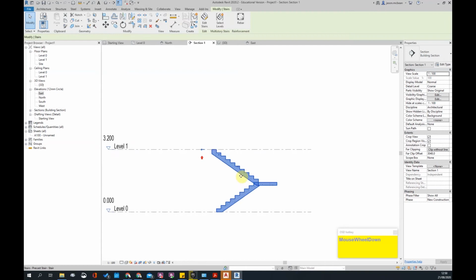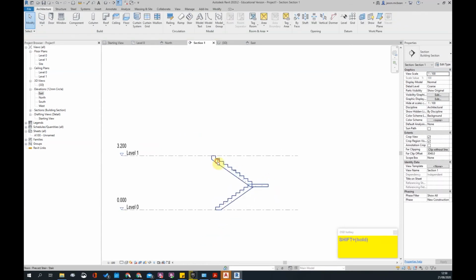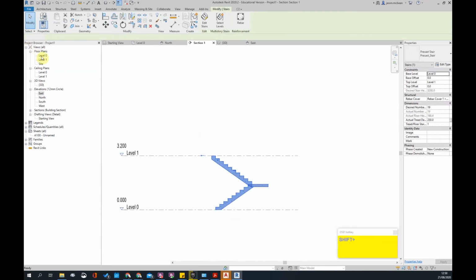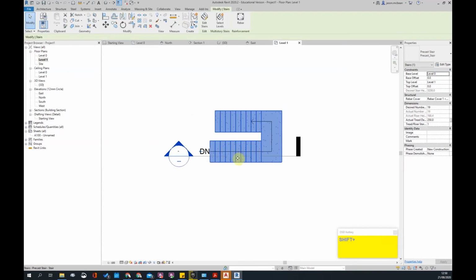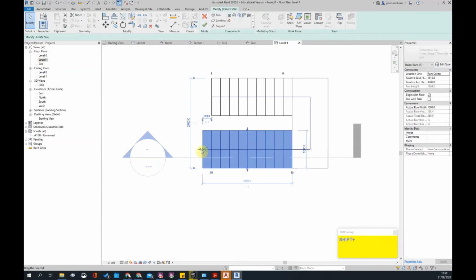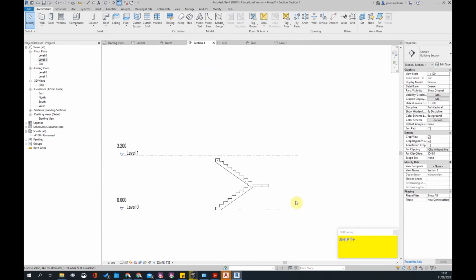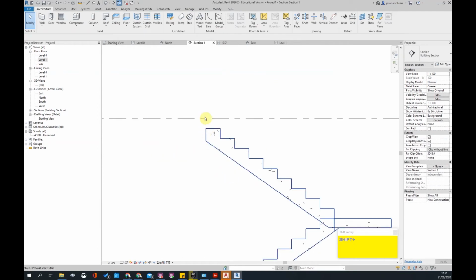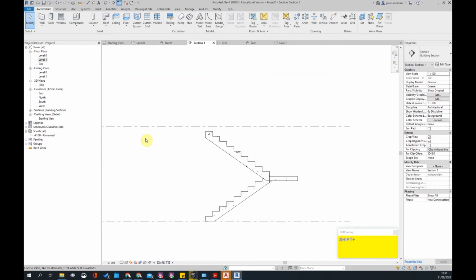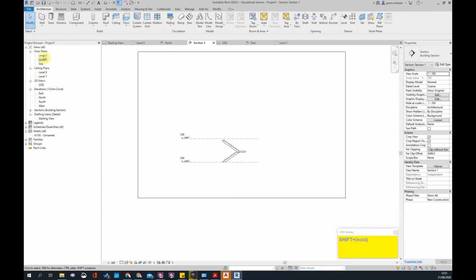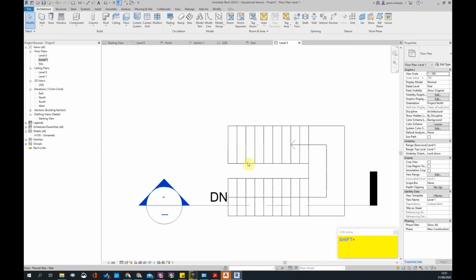So that's great. But what I tend to do is, because I've got a floor slab, I'll remove one of the risers. So I go to level 1, and I say edit stair, and I'm going to grab the stair and I grab the dot and pull it back to there. Perfect. Finished. I know that that's going to happen, but my floor slab will start somewhere over here and continue. Okay. All right. So in essence, my floor slab would have